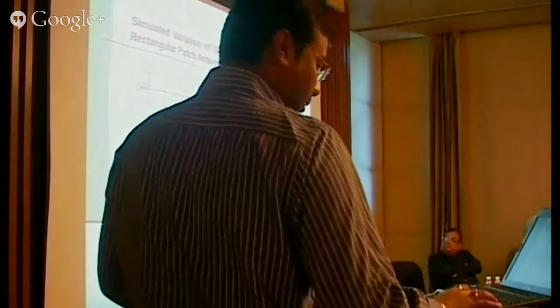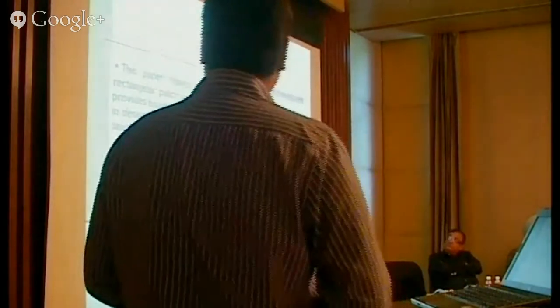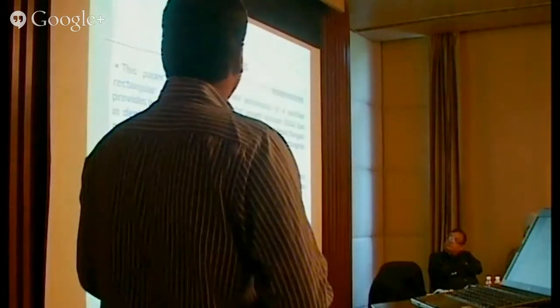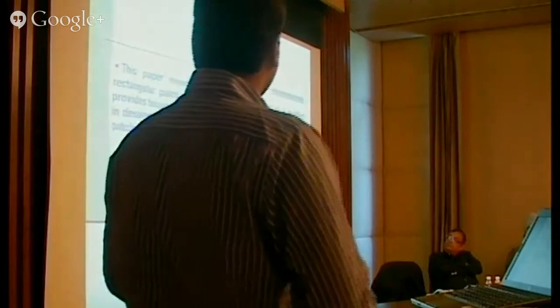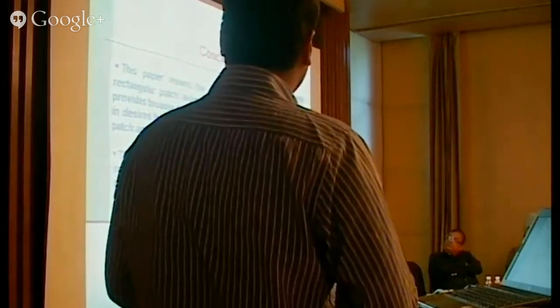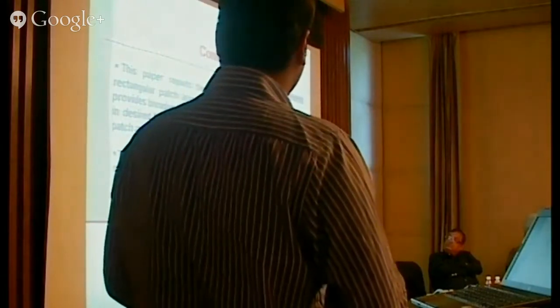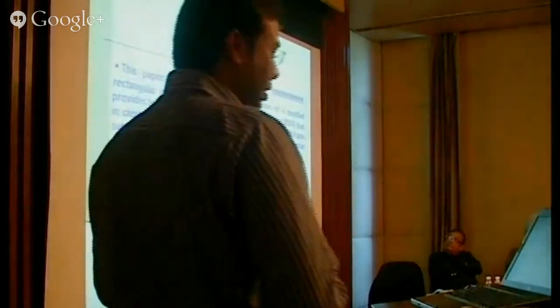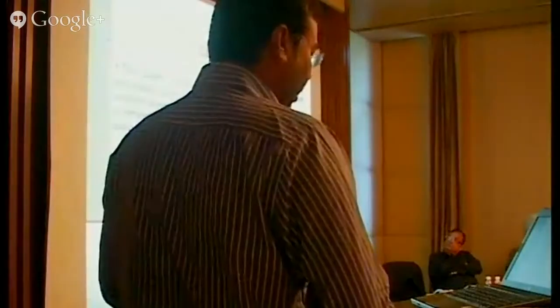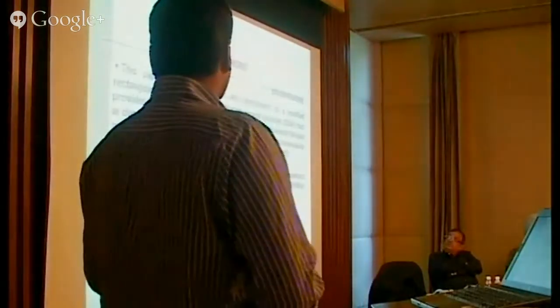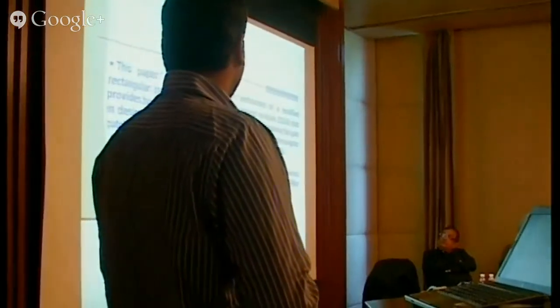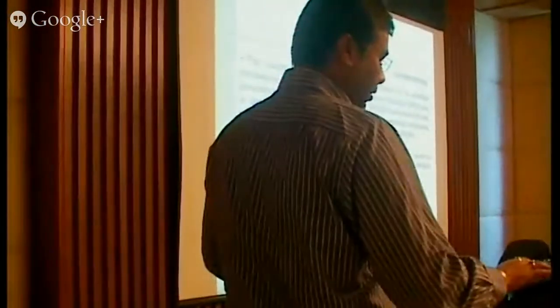dBi. The conclusion: this paper reports the design and performance of a modified rectangular patch antenna with defected ground plane structures that provide broader impedance bandwidth, nearly 2.6003 GHz, and nearly flat gain in the desired frequency range in comparison to the conventional rectangular patch antenna. The maximum gain for the antenna is close to 2.84 dBi. The proposed antenna may be used in modern wireless communication systems, including the lower band of wireless communication systems.